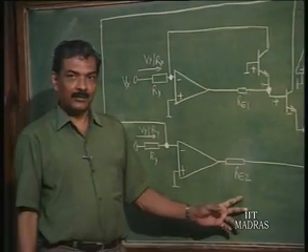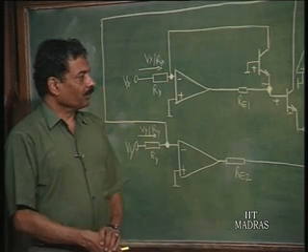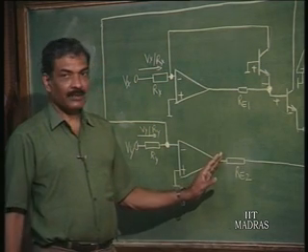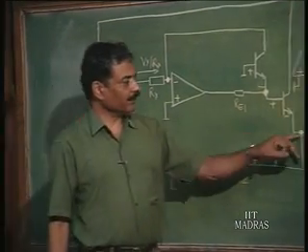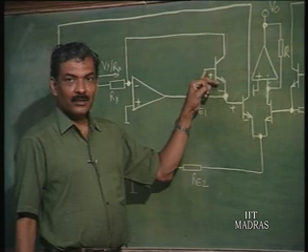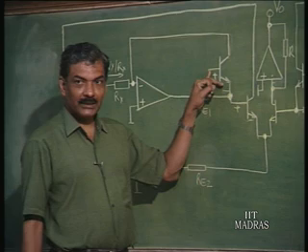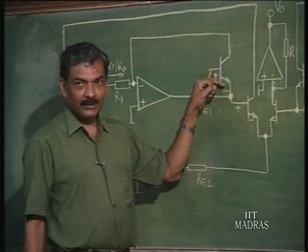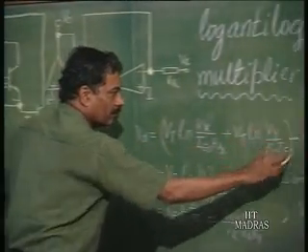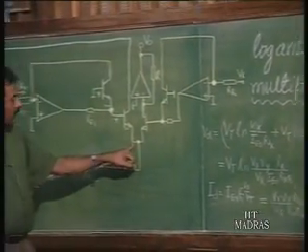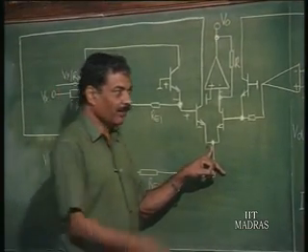Re2 has the same property that I mentioned about Re1, in order to make the frequency compensation become valid, and also in order to prevent the op amp from going to saturation in that attempt. Now that we have got here a voltage which is the summation of minus Vt log Vx by Rx into IE naught, minus Vt log Vy by Ry into IE naught here. This is what we got, of course only negative sign. So, this is a negative voltage. This is a negative voltage comprising of the sum of these.